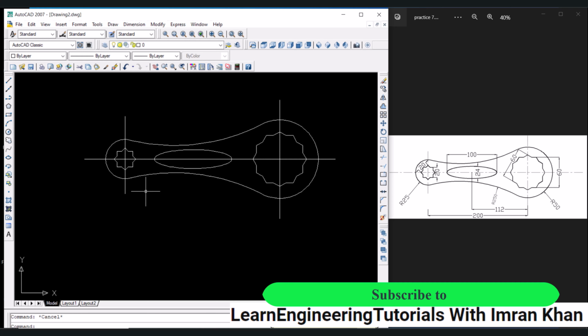Now if you can't see in this view, we have to use the LTS command, so LTS, enter, give the scale as 5, enter, press enter again, give the scale this time as 10, enter. Now we can see clearly the center lines. Now we have to perform dimensioning.